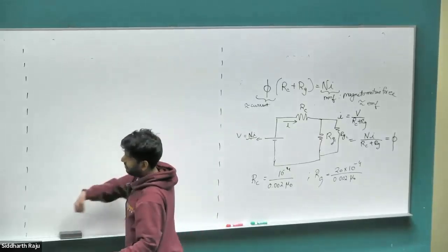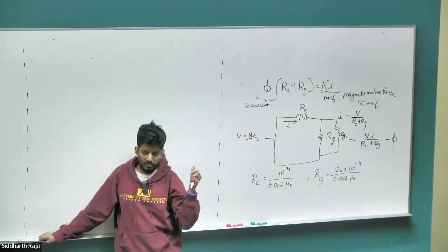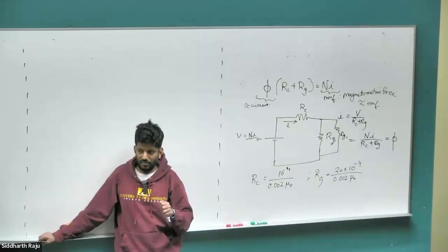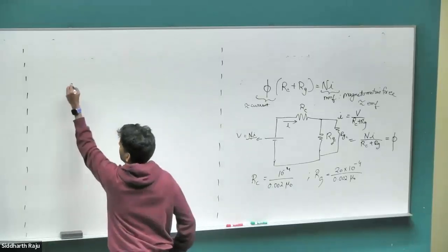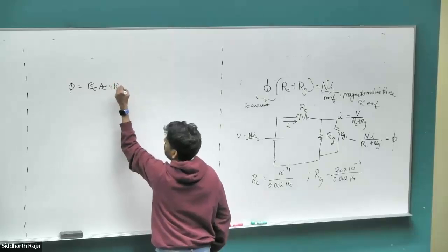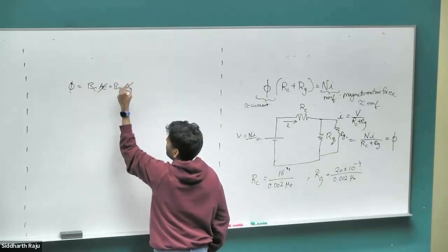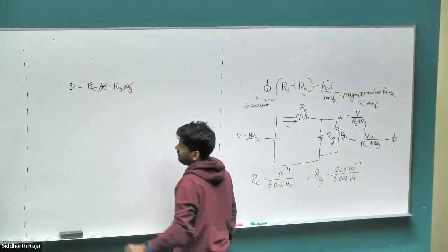What is going to be the B in the iron core, if you ignore fringing? Should be the same. Yep, it should be the same. Perfect. Because the flux was BC equal to BG. If I assume the fringing is not happening, then AC is same as AG, those go away. So BC is just equal to BG.